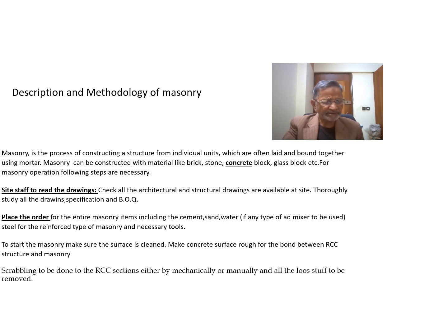All these materials are to be used, and before starting the masonry it is mandatory to thoroughly review the architectural and structural drawings, the BOQ, the specification, and the instructions of the structural engineers. Number one, the priority is that you have to place the order for the required masonry materials like bricks, stones, mortar, sand, and concrete blocks, etc.